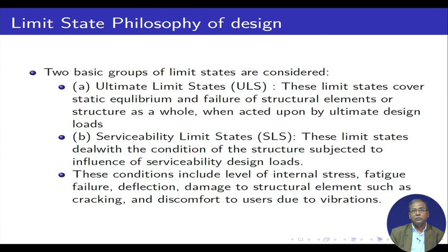These conditions include level of internal stress, fatigue, deflection, damage to structural elements such as cracking, and discomfort to users due to vibrations. So, these are called serviceability limits. One is ultimate limit state, another is serviceability: the limit state of collapse, as known in IS 456, and the limit state of serviceability. Here we say ULS and SLS.